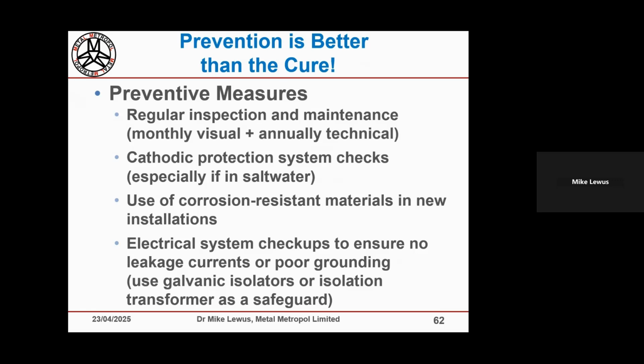Now, with small pits, say it's stainless steel whose passive layer has been undermined and even destroyed, and you get a lot of pits, and then you clean it and wash it out. Those pits have been formed by a reaction that produces hydrochloric acid in the pit. So if you wash all those out and take all the debris, I've certainly seen pits like that shiny. But that's not the same case that you're describing. I think you're describing one where these pits are much more macroscopic and you're getting a lot of shininess.